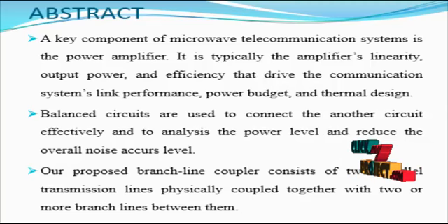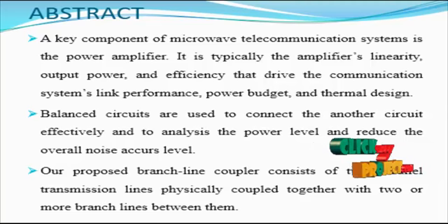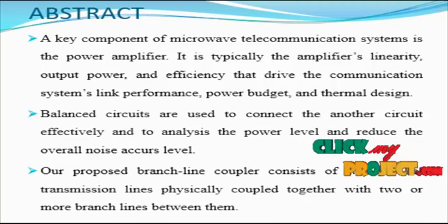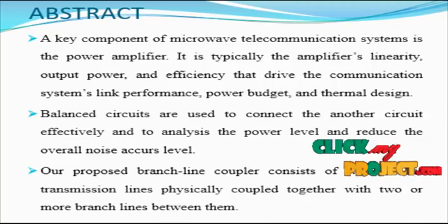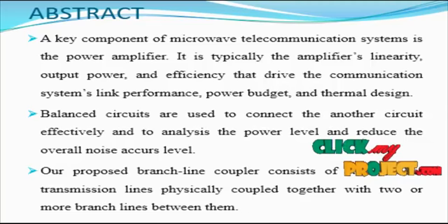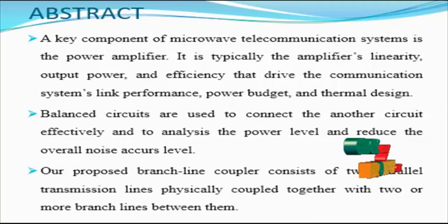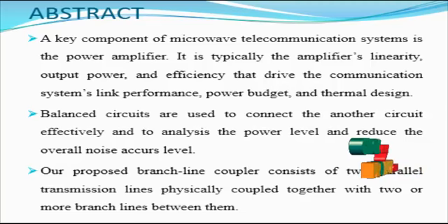In the balanced to unbalanced filter, the balanced to unbalanced power divider is also a basic component of such applications. Thus far, only a few papers about the balanced to unbalanced power divider have been reported. In this paper, a balanced to unbalanced Microstrip power divider based on branch lines with several steps and one resistor is proposed. The functions of power dividing, frequency selectivity, isolation between the output ports, and common mode suppression can be realized at the same time.